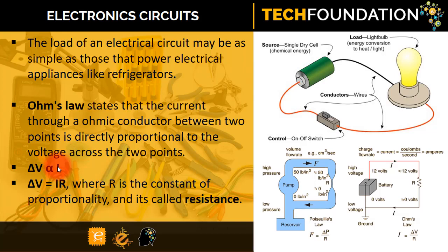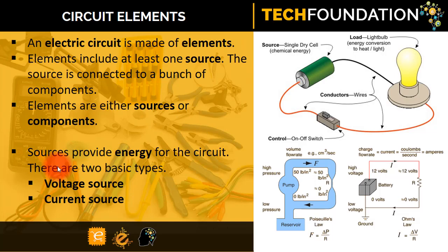All right, so power in electric circuit is the product of voltage and current. Remember also that power is energy per unit time. So for a resistive element, this power is usually dissipated in the form of heat in the material. This causes a rise in temperature, and hence depending on the temperature coefficient of the material, there will be a change in resistance. For Ohm's law to hold, it requires that resistance remains constant, and this limitation is very important in circuit design.